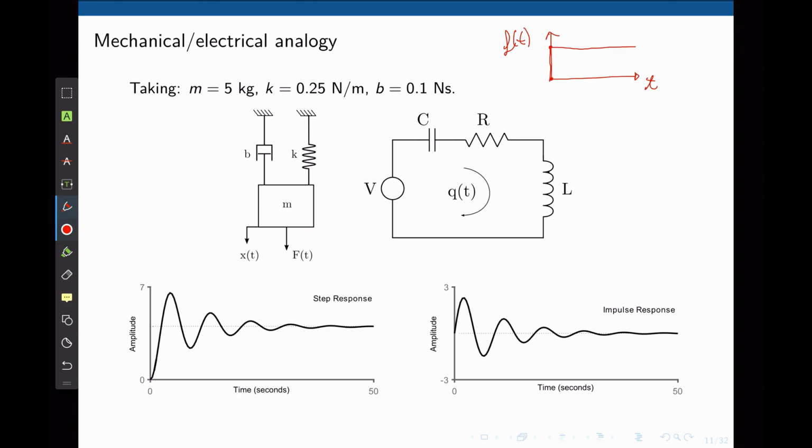It will have some inertia because of the kinetic energy in the mass. The spring and the damper are holding it back. And at the point where the force we apply and the reactive forces due to the damper and spring balance out, the mass stops moving. It first oscillates because of inertia.